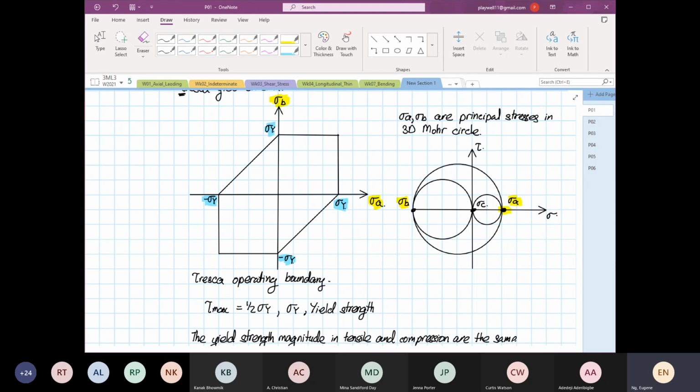Okay, civil engineering, you don't, and if you are doing design for concrete, this is not the one to use. The one to use is Mohr's criteria, which I don't have time to cover. But the working principle is the same. There are generally three very popular ones: Tresca's, Von Mises, and one more, Mohr's criteria.